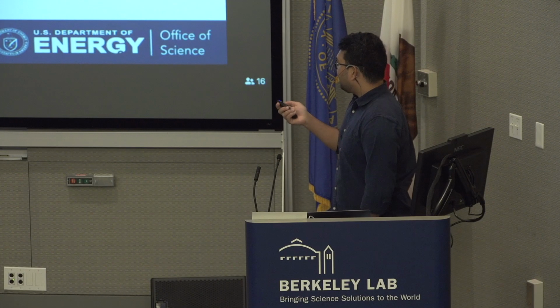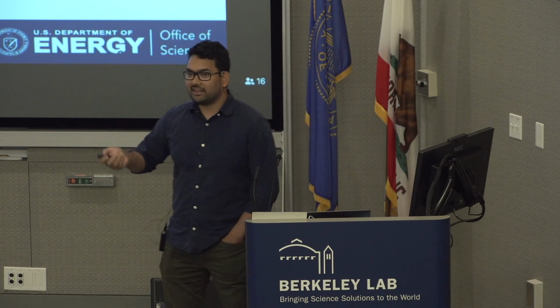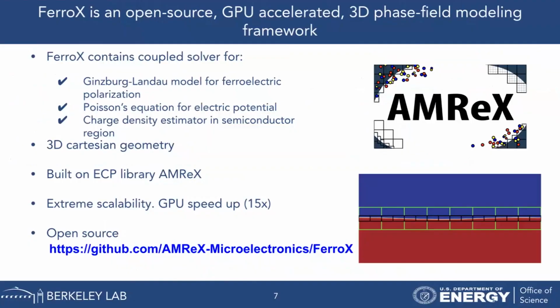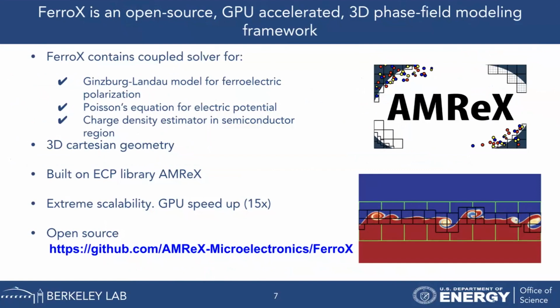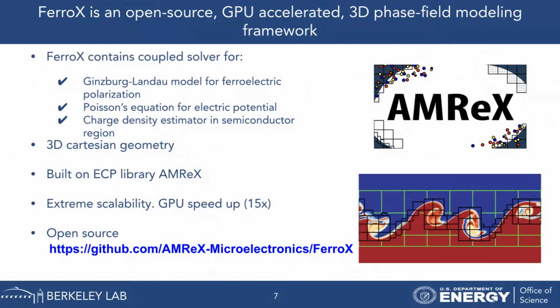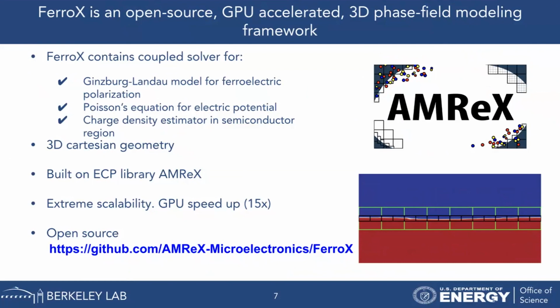So with all that in mind, we started the development of this code called FerroX, Ferroelectric Device Simulation at Extreme Scale, about a year and a half ago. So let's look at this code called FerroX. It's an open source, GPU accelerated 3D phase field modeling framework. It solves all the physical equations that I mentioned in the previous slide, in the ferroelectric layer, in the overall device, and in the semiconductor region.